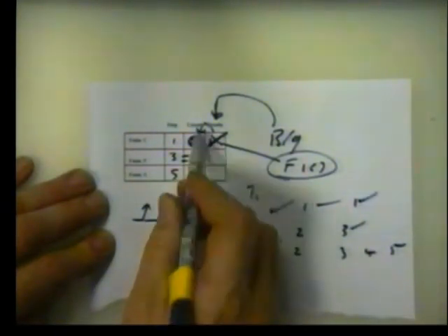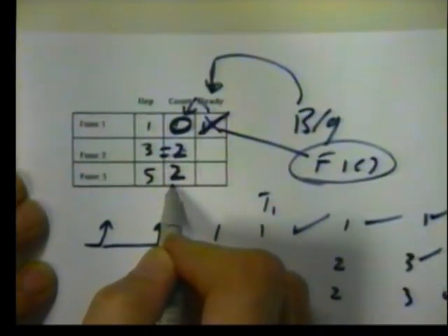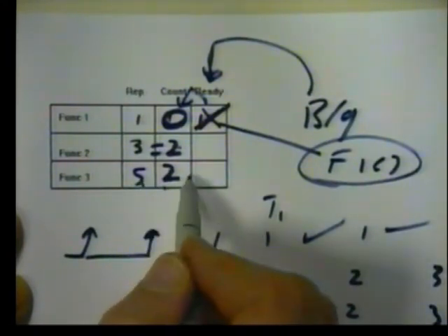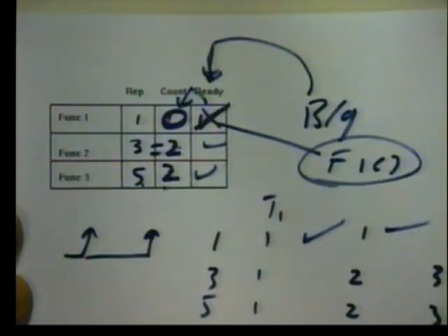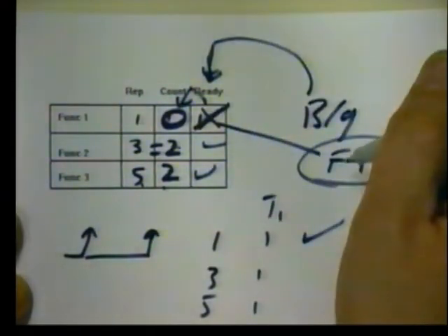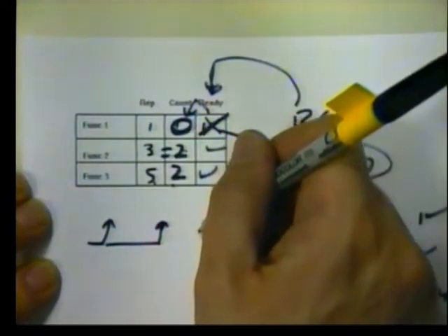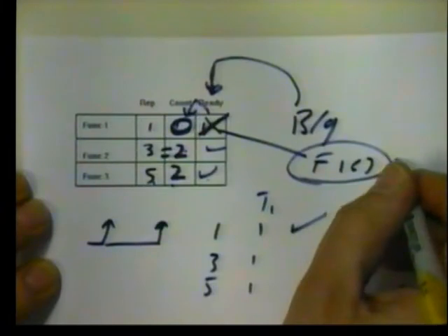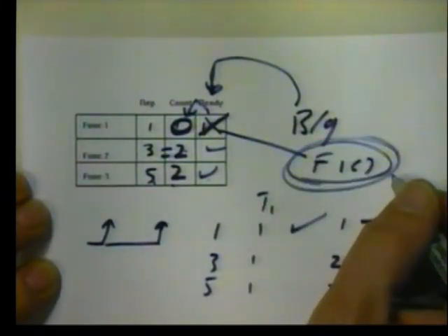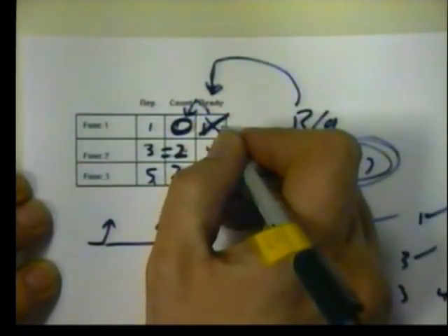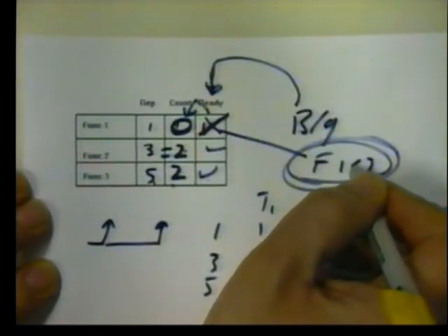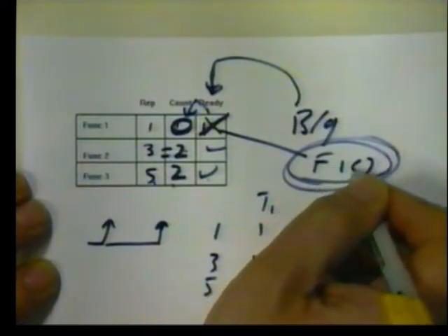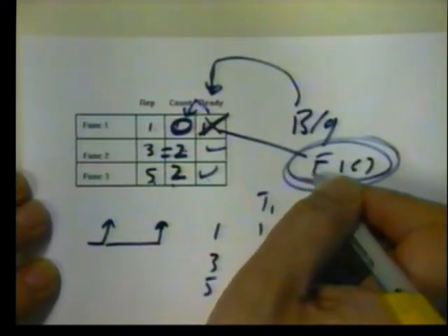So every time we come into the interrupt routine, we increment the count field. When the counter equals the repetition rate, the function is signaled to run. The background routine, its job is it just scans the ready field. That's all, that's its signal. Whenever any of these are signaled to run, it just calls the relevant function in a table. So it says, if function 1 ready is true, execute function 1. If function 2 ready is true, execute function 2. Very, very simple bit of code.